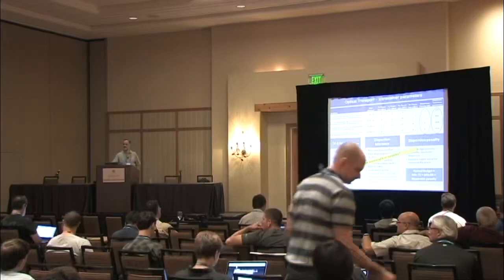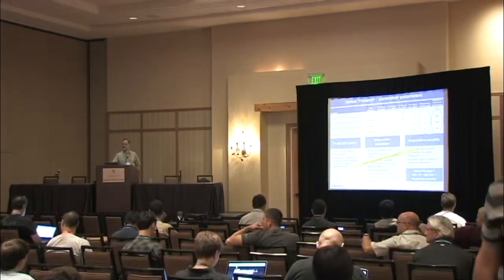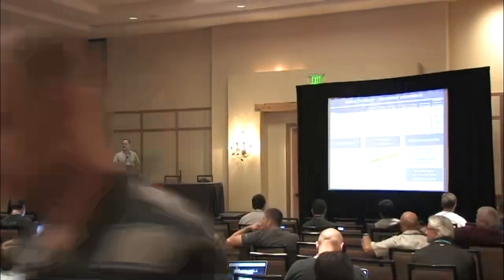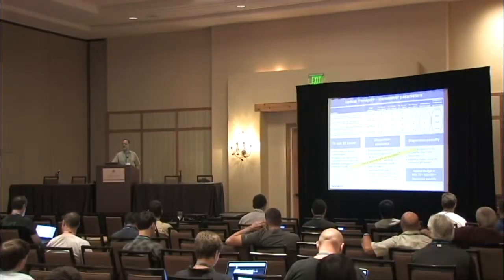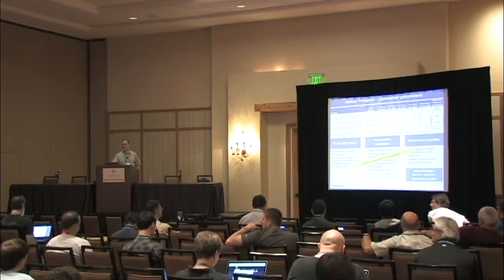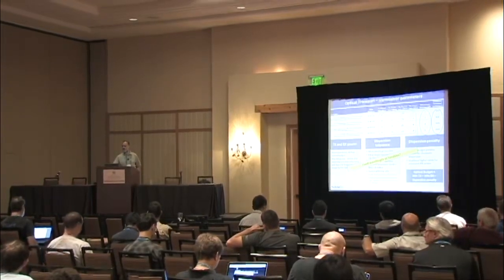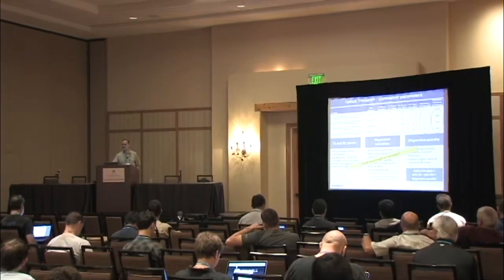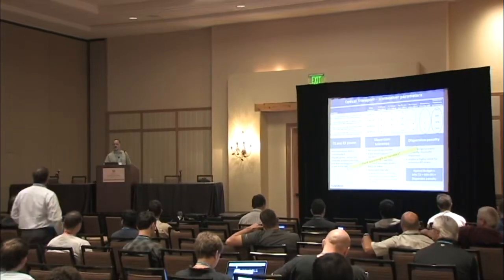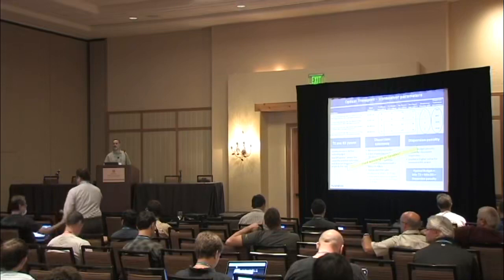The other advantage of that is the fact that the tunables usually output slightly higher power and help us be able to push the signal a little bit further. On some of the paths that we're on, either we're extending maximum distance or the only path we could get was the only path we could get, and we had to take whatever was there. Sure. Tunables in general can be amplified to about 6-7 dBs more than fixed wavelengths. So reach is an issue, yeah.